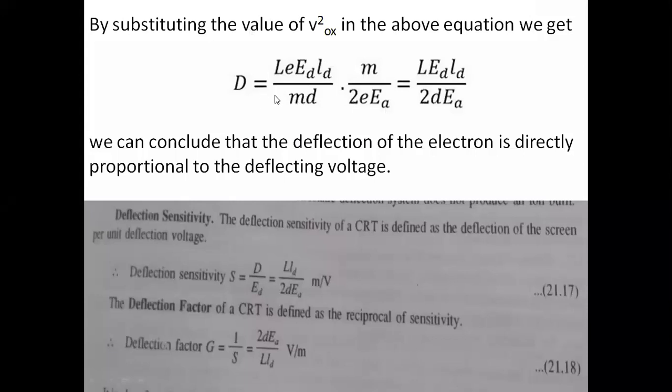The deflection of the electron beam moving in the vertical deflection plates depends upon the potentials applied on the deflection plates. Similarly, the horizontal deflection plates have the same situation, but in place of vertical movement, the beam moves in the horizontal direction. Like this, the deflection of the beam of electrons on the screen of the CRT depends upon the potentials applied on the deflection plates.